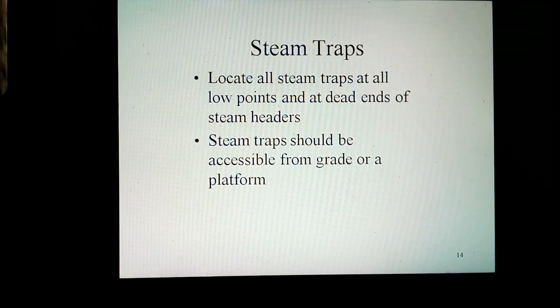Steam traps. Locate all steam traps at all low points and at dead ends of steam headers. Also, provide traps periodically on excessively long runs of steam piping for sufficient condensate removal and to ensure dry quality steam at destination. Steam traps should be accessible from grade or platform. Steam traps located in pipeways should be considered accessible by portable ladder.